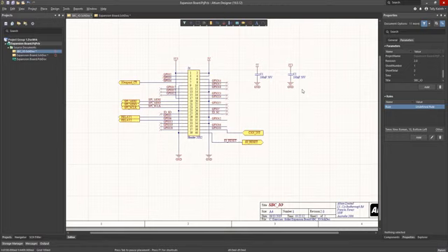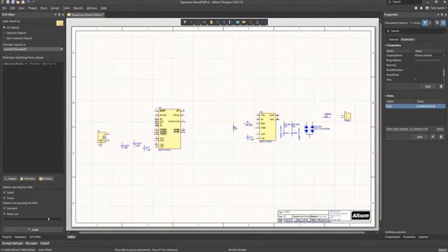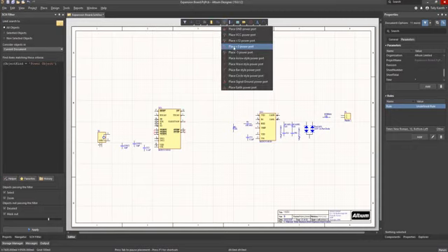Now at this point we will jump ahead, skipping over the repetitive steps of placing components from the different libraries. We can now shift our focus to adding wires, net labels and ports. We will start by adding power and ground ports. As previously mentioned, power ports provide global connections spanning all project schematics. Right-click on the ground icon in the active bar menu and select the port +5.